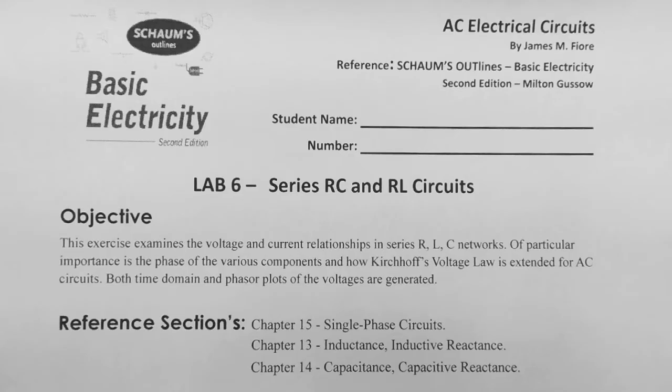Under Objective, it says this exercise examines the voltage and current relationships in series RLC networks. Of particular importance is the phase of the various components and how Kirchhoff's voltage law is extended for AC circuits. Both the time domain and phasor plots of the voltage are generated.